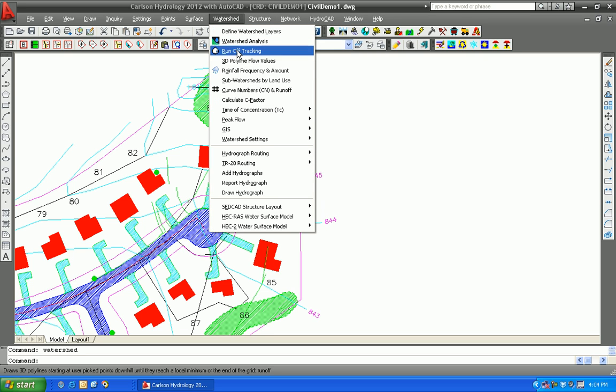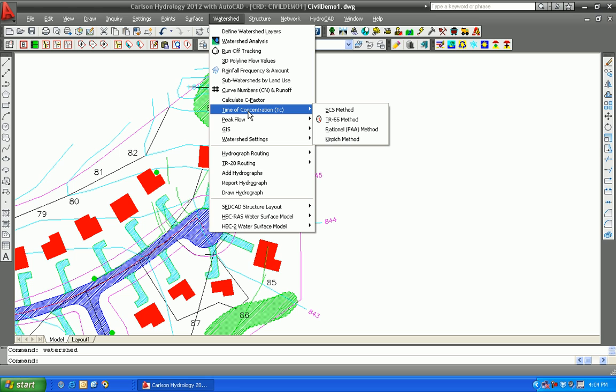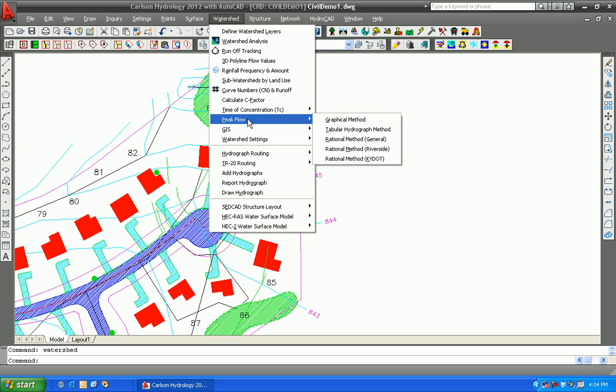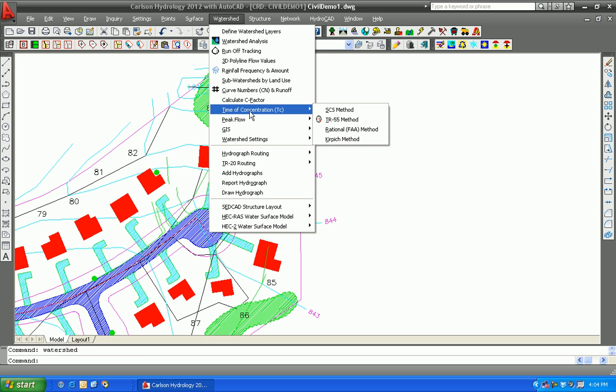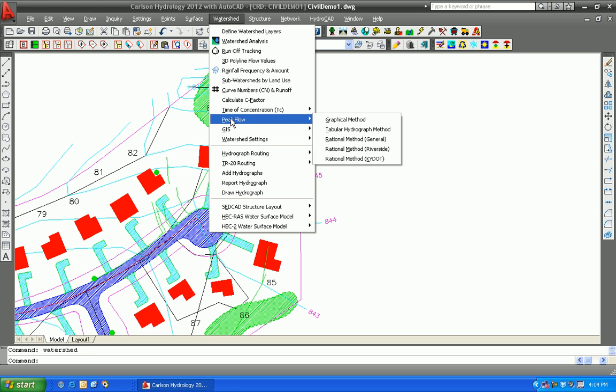We've already seen it applied to the calculation of the C factor, which along with time of concentration can lead to a peak flow calculation. And you do the peak flow before and after construction. So each of these parts, C factor and time of concentration, are done before and after construction, so you can compare peak flows prior to and after the construction. Often done to size detention ponds.